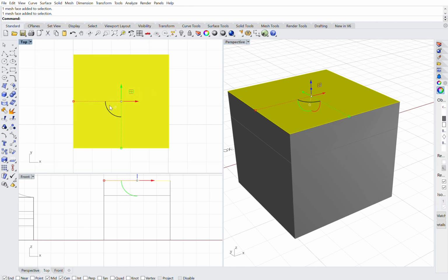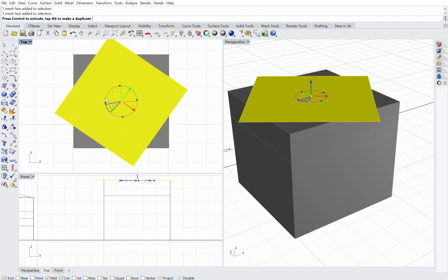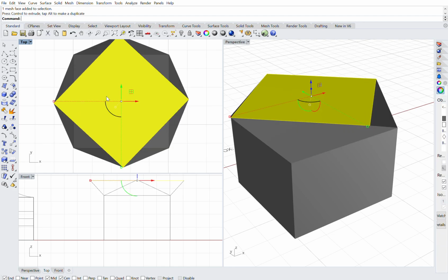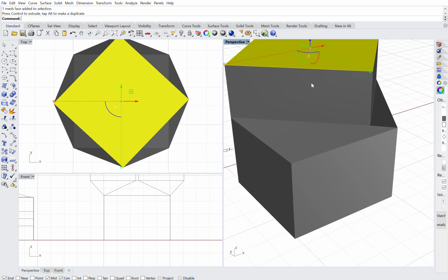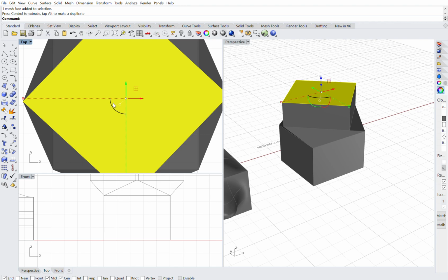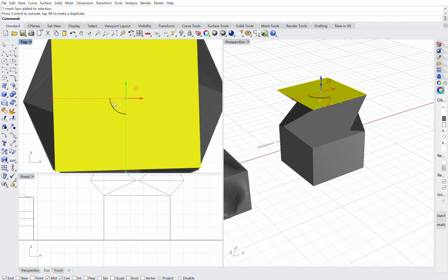Let's do again similarly. You can drag this kind of on plan view. You can drag it around and rotate it. Okay, let's rotate that. Another way, instead of just randomly dragging that point, you can type in. So click on the point and type in a figure 20. That's fine. Similarly for the rotation, you can put in a value there, plus 45. That's fine.